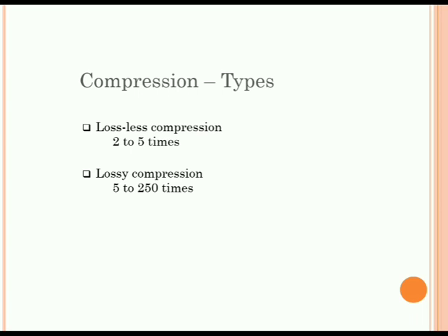Now let us consider a video that has more motion. In that, more pixels can change from one frame to the next frame. When more pixels change, the video compression scheme must send more data to keep up with the large number of pixels that are changing. If the video content includes an explosion or flames or flocks or thousands of birds or any other image with a great deal of high frequency detail, the quality will decrease or the bitrate must be increased to render that information with the same level of detail.